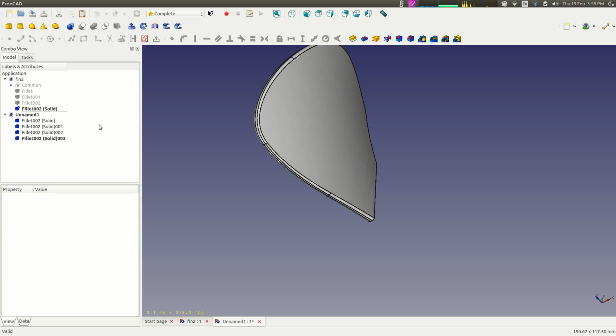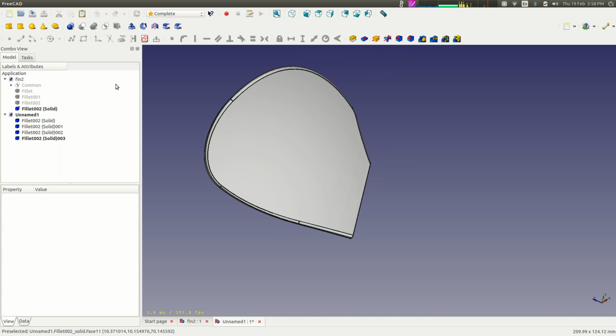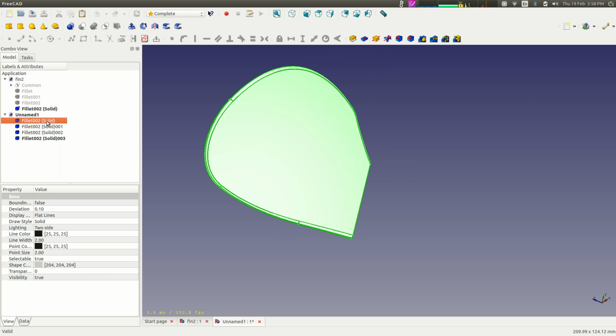So now I'm going to adjust the placement of these, where they exist in our space here. I'm going to leave the first one where it is, and I'm going to rotate the other 3 about the y-axis, right? I'm going to rotate one 90 degrees, another 180 degrees, and the other 270 degrees. Since I've pasted 4, there should be 4 fins all 90 degrees to each other. And if you want to do 5 fins, then you would just rotate it by whatever the angle difference is. So 6 fins would be 30 degrees, right?